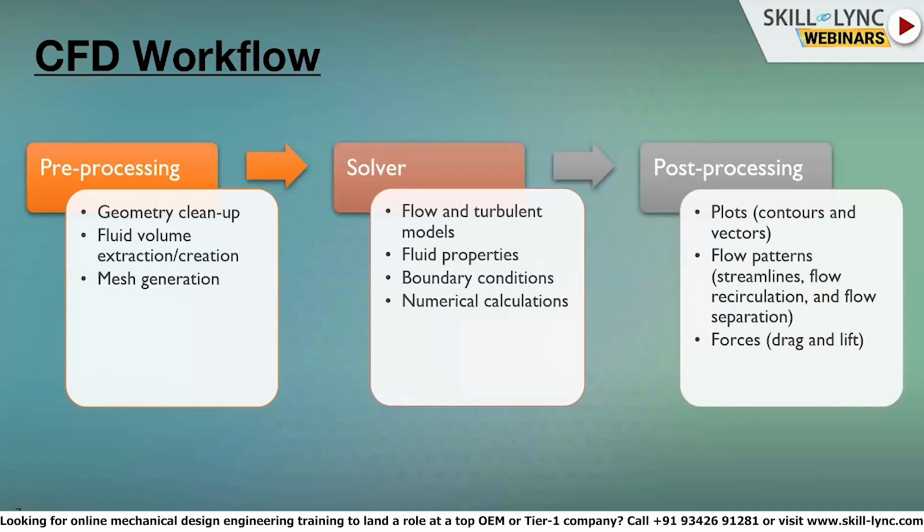The pre-processing involves, so from the designer, one may receive the geometry, then he may need to know what is required for his CFD problem. Those domains he has to extract, clean up other things. Then he has to extract the fluid volume. He has to define the inlet, outlet, or other boundaries. He has to generate surface mesh and volume mesh. Then the quality has to be cleared for both surface mesh and volume mesh based on the type of the mesh. Then after that, the solver settings part will come.